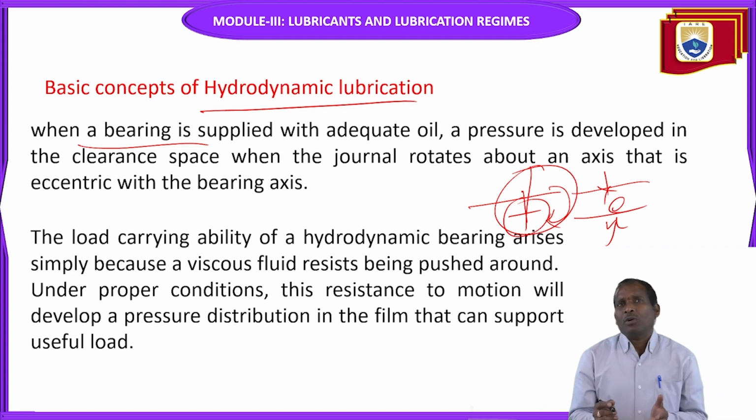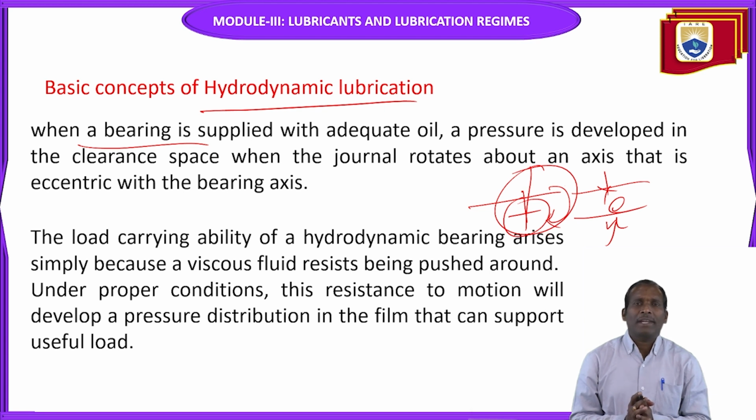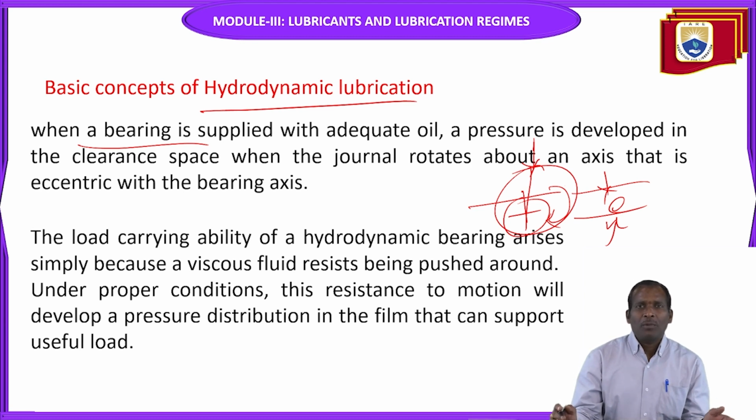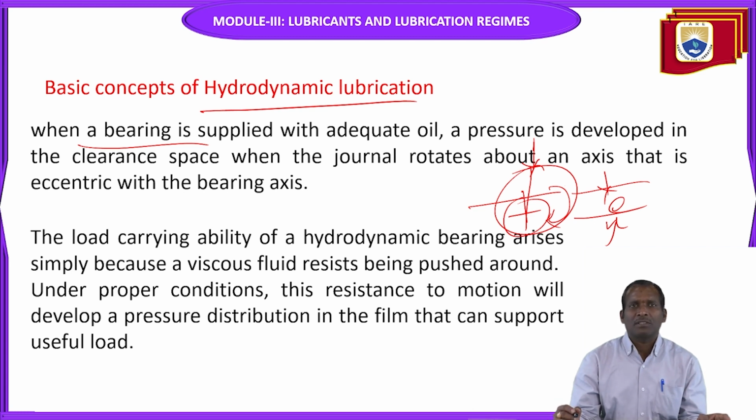So the pressure is developed in the clearance between these two surfaces. The load carrying ability of a hydrodynamic bearing arises simply because a viscous fluid resists being pushed around. So whenever this bearing is loaded, under proper conditions, this resistance to motion will develop a pressure distribution in the film that can support usable load. Whatever the pressure developed inside the contact between the two surfaces, a sufficient pressure will be distributed to support